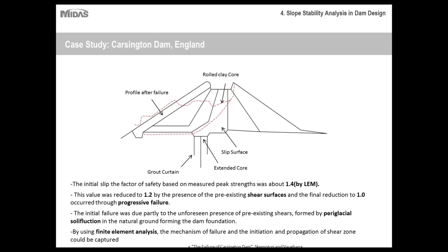They saw that it was something very useful and actually very necessary for projects such as these. That's why this particular case study is so important, because seepage analysis and slope stability analysis are very linked when it comes to dams and embankments. When seepage analysis is used in a coupled analysis with either the limit equilibrium method or the shear strength reduction method, you can get results that are more accurate and that safely take into consideration pore water pressures or changes in pore water pressure.